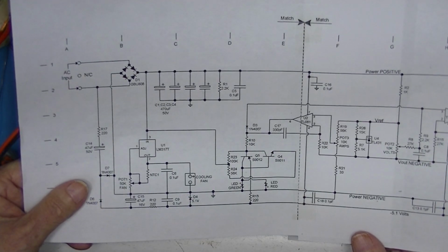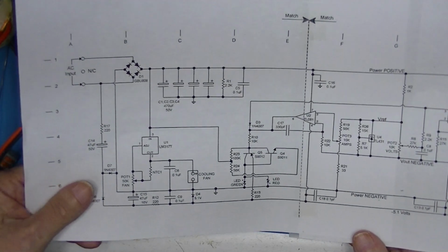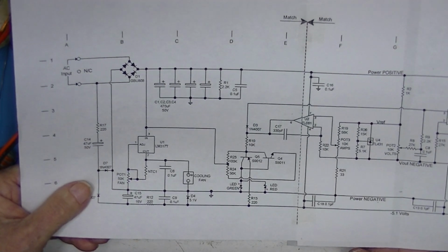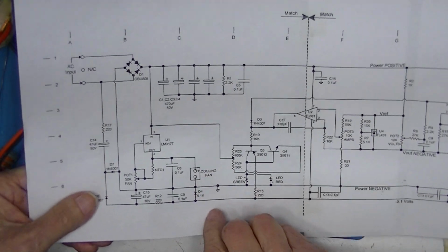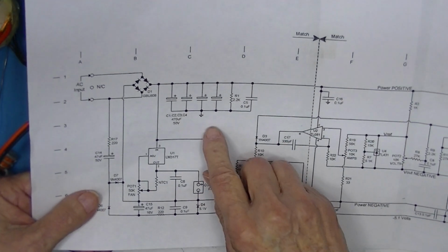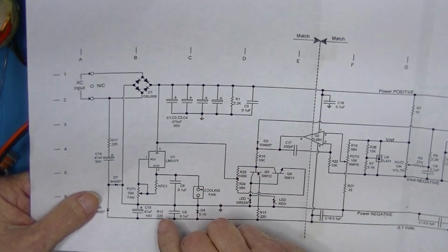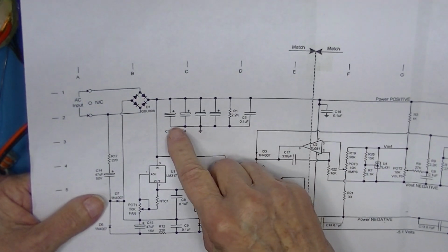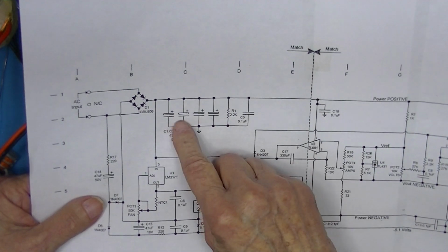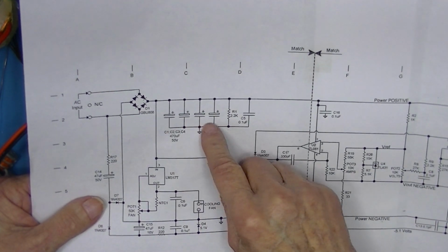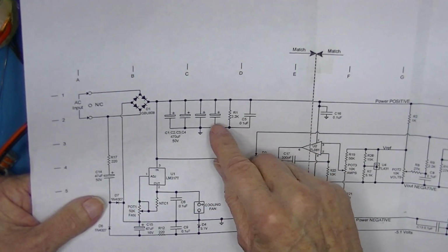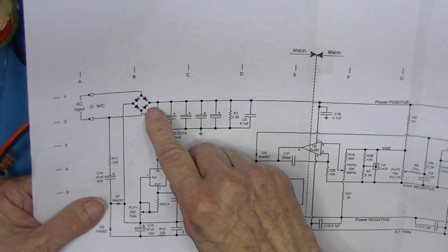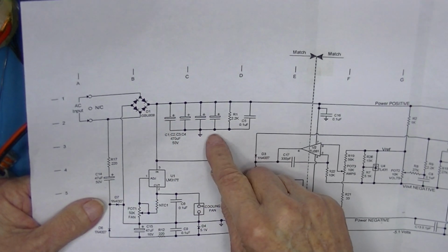Now, I've said that I did not consider this supply capable of 5 amps. I'll give you 2 more reasons. The first one you have to verify by doing a little studying, but a 50 volt and lower power supply that delivers 5 amps typically needs 6,000 to 12,000, I've seen 18,000 microfarads of input filter capacitors.